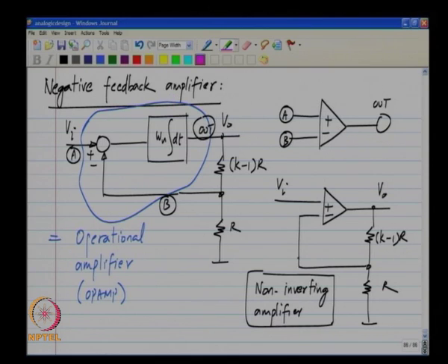Now, if you look at the circuit elements that we have, resistors, capacitors and inductors, and we can also make a variety of controlled sources using transistors. This you are already familiar with. You have a common source amplifier, common gate and common drain, and some of them are useful as voltage controlled voltage sources and some of them as current controlled current sources and so on. And the transistor by itself acts as a voltage controlled current source. Either the MOS transistor or the bipolar junction transistor acts as a voltage controlled current source.